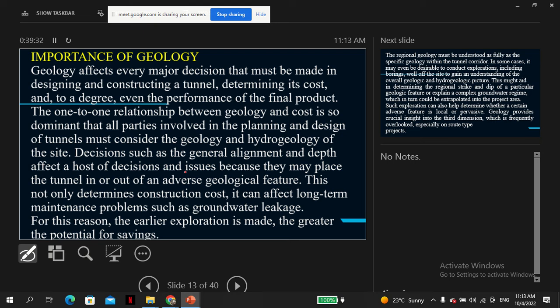In fact, you remember one of the factors that affect the construction is that you need to consider that the TBM, the tunnel boring machine, can negotiate corners. So because of these alignment requirements, basically for safety, you might find that the route is heading towards maybe a hazardous material, or maybe a place where there's a fault, or maybe a place prone to volcanic activity, things like this.